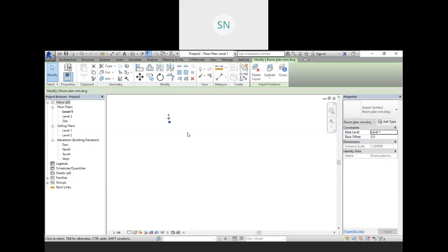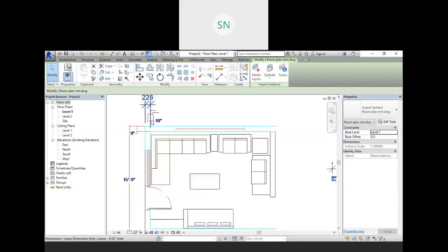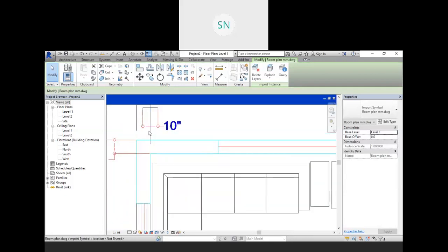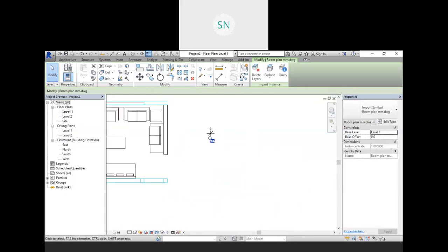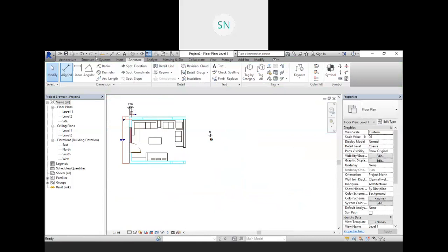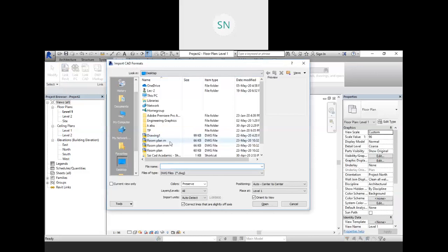Okay. Now again let's insert our meter file. So this same drawing, this is 10 meaning 10 inches. Here we have 10 meaning 10 millimeters, and again click on the insert, import and choose this meter file. Unit is again auto direct. So over there we chose 1 means 1 meter in our AutoCAD file, right?